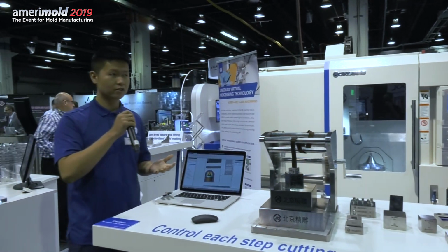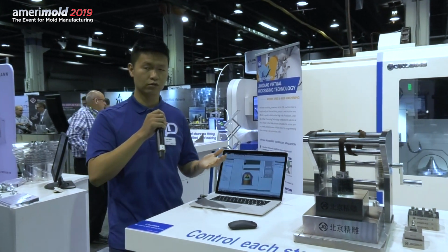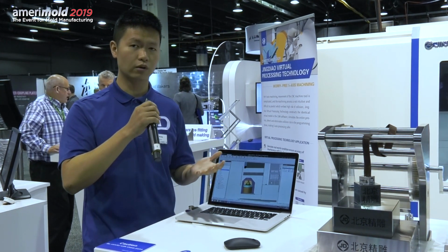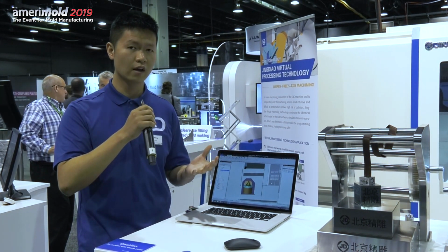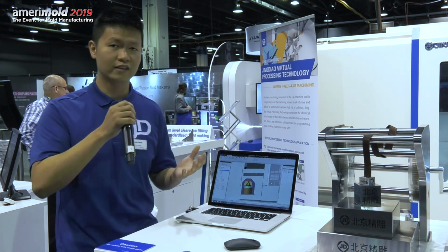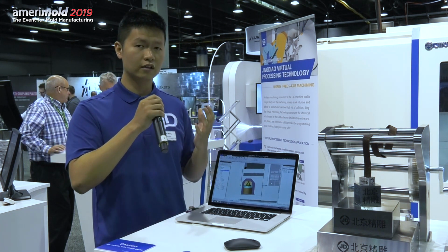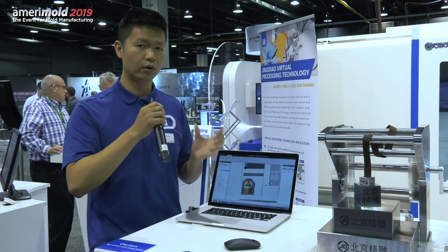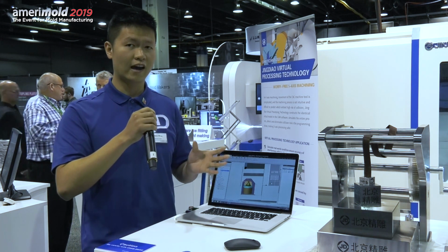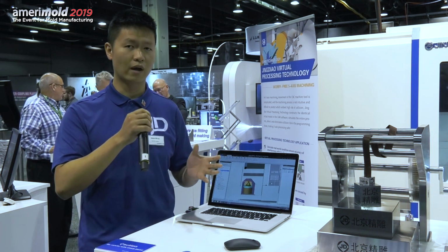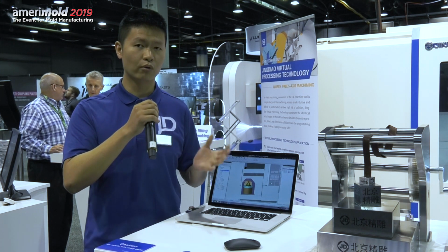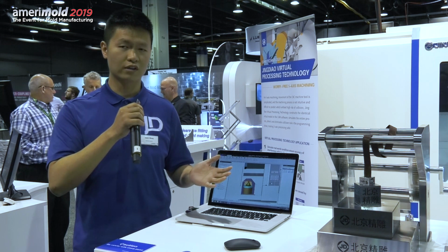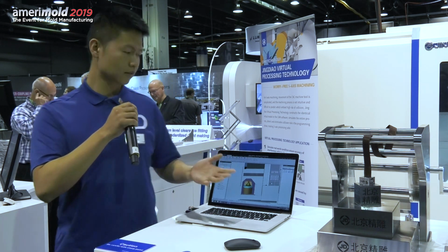So for 5-axis machining, the movement of the machine is too complicated, and machining process is non-virtual and difficult to predict the risk of the collision. So in Jingdiao virtual processing technology, we construct the virtual model in CAM software. We can simulate the programming and detect and eliminate the collision in programming phase, make 5-axis programming safer. So let us give you a basic introduction about our CAM software.